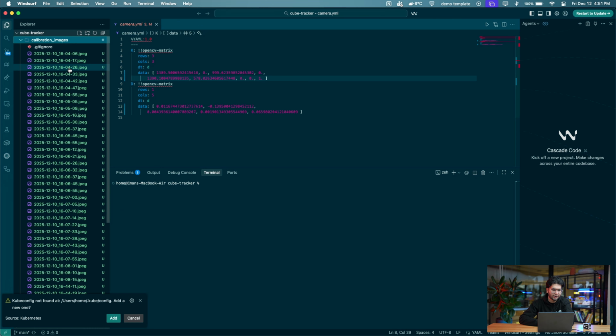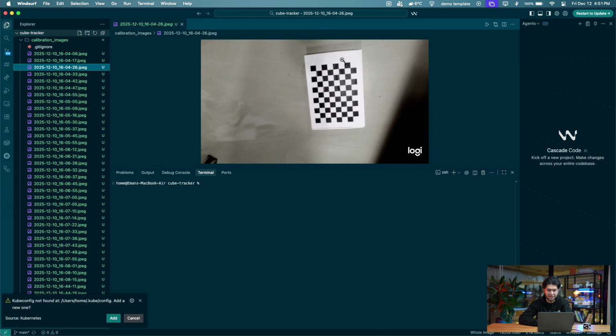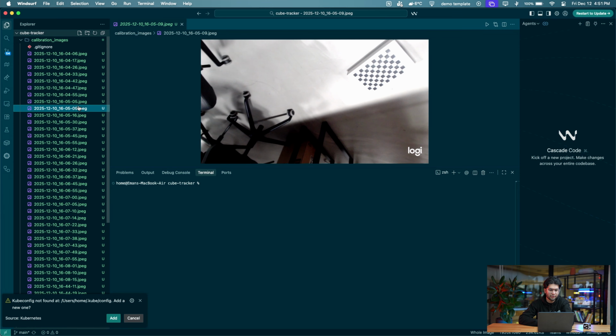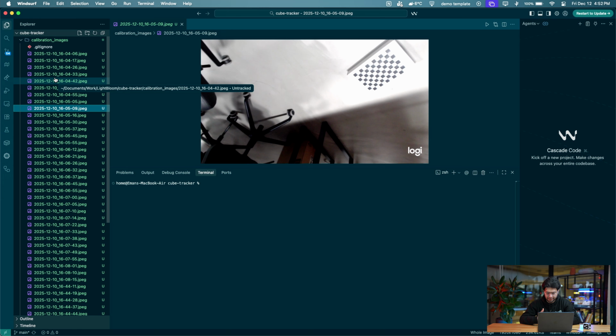But now it's more calibrated, and we have calibrated the camera by taking different pictures. If I can show you, for example, here we have different images of the checkerboard. We took 50 different images of this checkerboard, and we calibrated the camera. Before doing this, the camera was just seeing blurry images. For example, assume a human without glasses: we can see just blurry images of the people standing in front of us, but we didn't know where they are standing or what their exact position is.